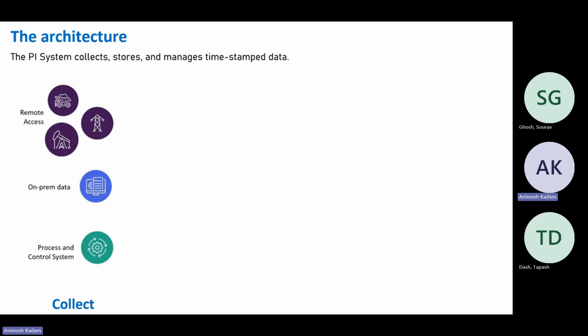Then another thing is the upper and lower limit. Your upper and lower limit is not coming from anywhere, though your set points are there. Though you will be changing your set points, you need to mention your upper and lower limit. Suppose my set point is 50. How much deviation is allowed for that particular parameter? If my set point is 50 and only 1% deviation is allowed, in that case my upper and lower limit will be 0.5.